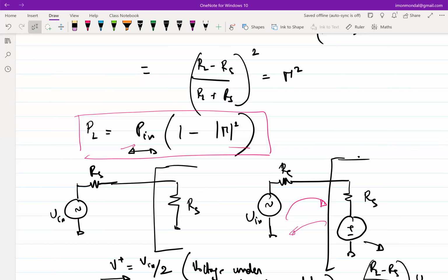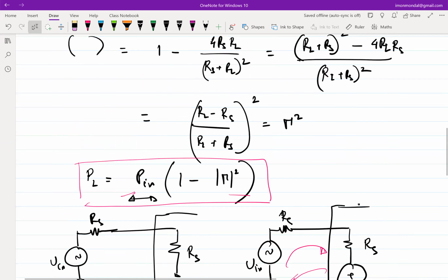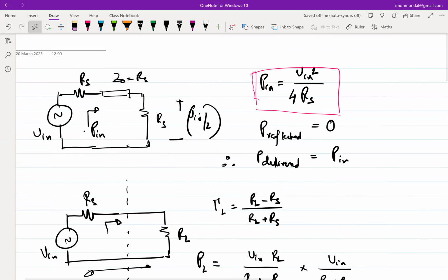You will be deriving maximum power. Yes, that's true. But that maximum power will not be, okay. So in that case, okay, I understand what the problem is. The maximum power in that case will not be equal to V squared over RS. It will be the real part of basically, in that case, when you are saying Z is equal to Zn star, which means you are assuming that the source has a complex load also, complex impedance also. Otherwise, you cannot have a match, right?